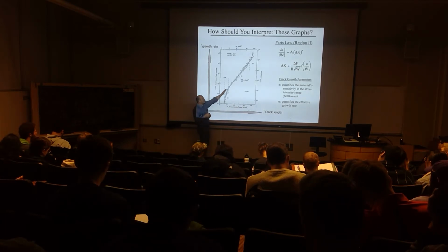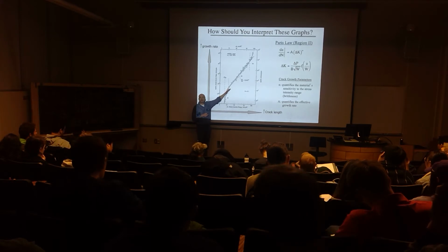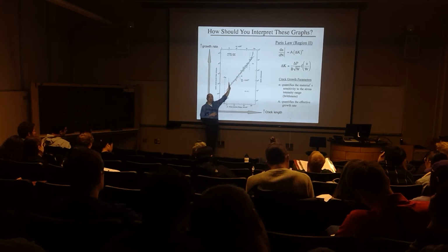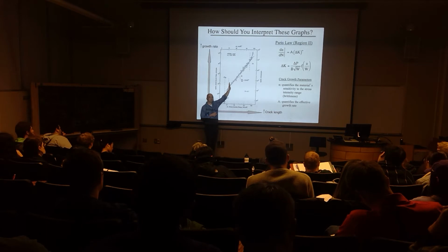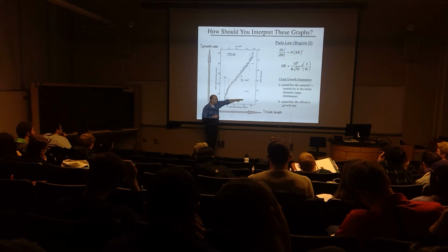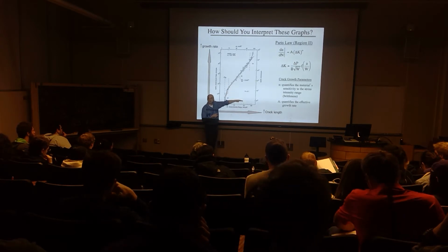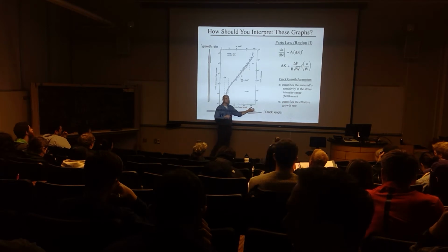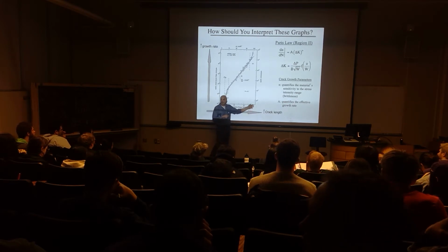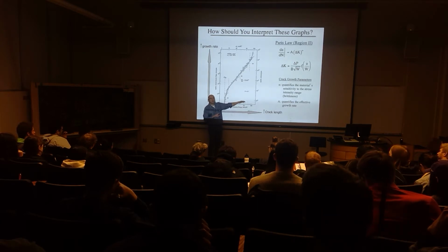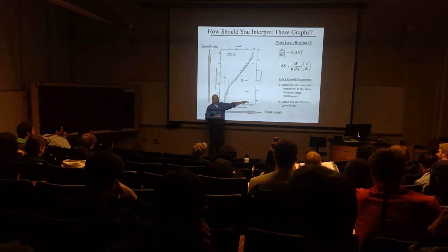The other thing you want to look at is slopes. Slopes say something very important about this response. Let's say that I have a slope that's very high. What does that tell you? It's almost vertical. Let's compare it to a slope that's almost horizontal. This is the easy one to think about physically. If the slope is horizontal, it says that regardless of the fact that the stress intensity is increasing as a function of the increasing crack length, the material doesn't care. Oh, that's a beautiful response of the material. I'd love to have that material for my structure.